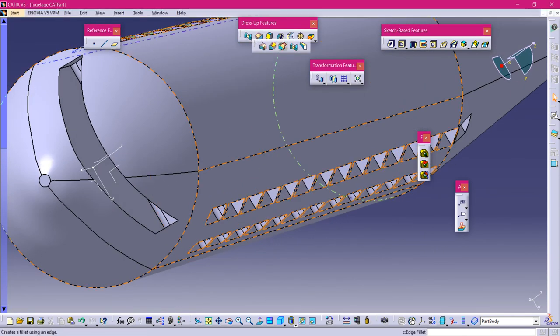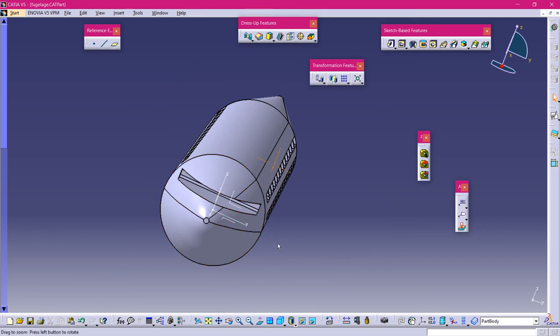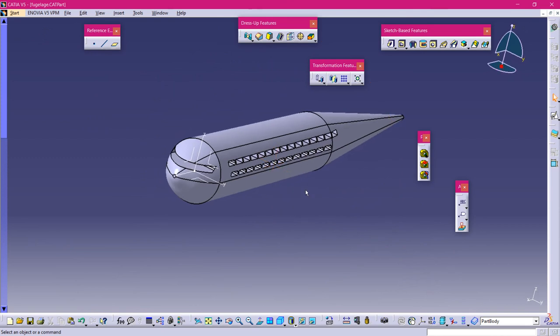Similarly, all these edge fillet variable radius, that means here you can give one radius at one point and another radius after some distance. And this is chordal fillet, that means you can give a chord length, then the fillet will be obtained according to that radius. And then face to face fillet, that means I have told you now, that's face fillet. Tritangent fillet is also similar to face fillet. You have to select two faces and the middle face will be removed. For example, while designing the wing, I will be showing you using tritangent fillet and draft, chamfer, shell, everything.